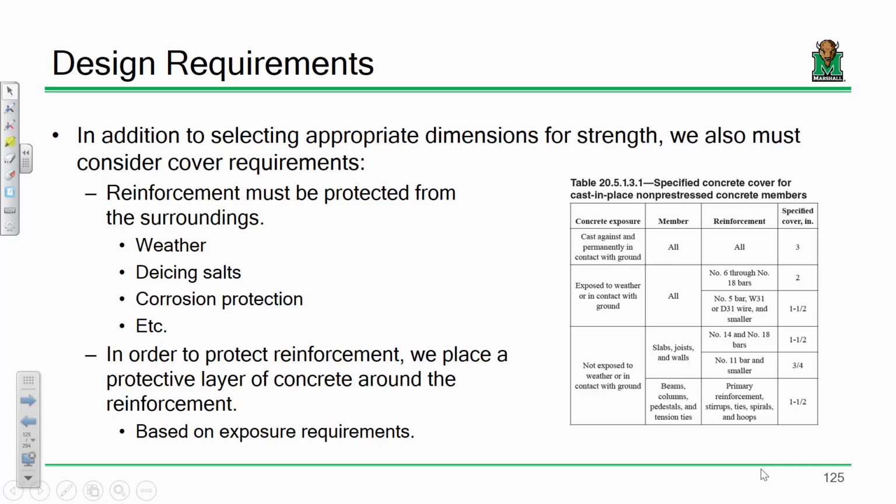If any of you have ever been on any DOH jobs and you see a concrete beam and it has some significant cracking, there's a good bet that maybe that reinforcement's starting to corrode. Once there's some water or chloride penetration on that rebar and it starts to corrode, the concrete cracks as a result, and then that cracking leads to a larger void, which leads to more water and chloride penetration, which leads to more corrosion, which leads to more cracking, and so it just sort of builds on itself, and it gets out of control. So it's a bit nuts.